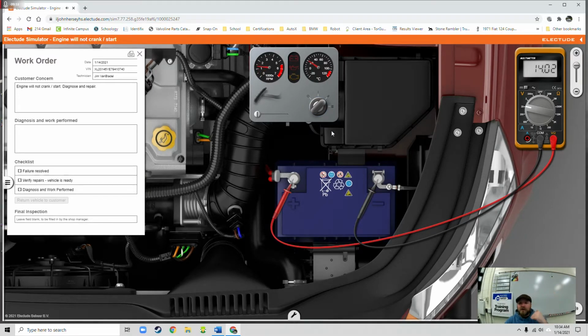We saw it drop to 11.5 or somewhere around there, and then now we see that voltage jump up to over 14. That 14 volts is the charge coming from our alternator. Our alternator is pushing current and voltage, I guess, to our battery to make sure that it gets replenished from the energy that it used to start the car.